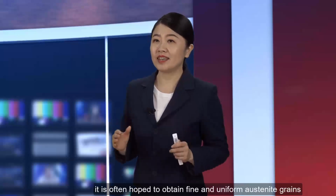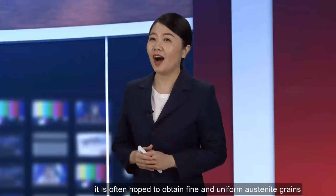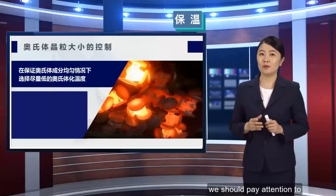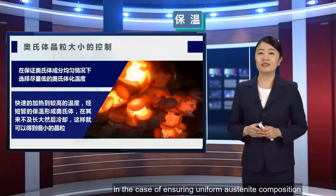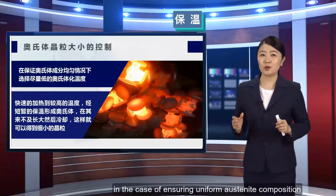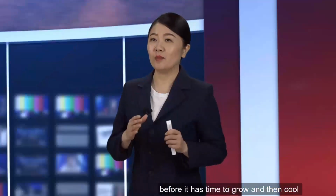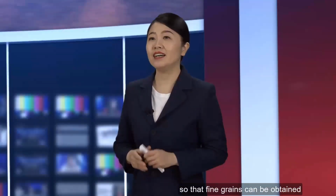In engineering, it is often hoped to obtain fine and uniform austenite grains. Then when heating and heat preservation, we should pay attention to, first of all, in the case of ensuring uniform austenite composition, choose the lowest austenitizing temperature as possible. Second, quickly heat to a higher temperature. Austenite is formed after a short holding time, before it has time to grow and then cool, so that fine grains can be obtained.